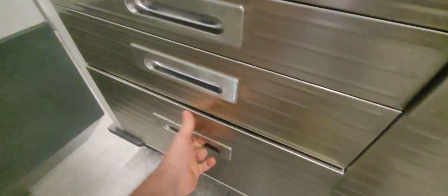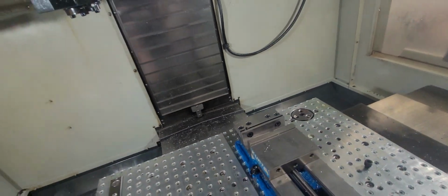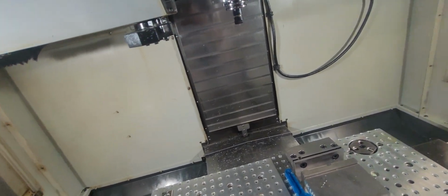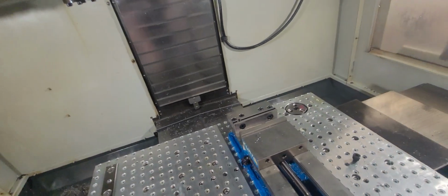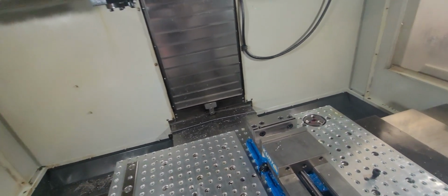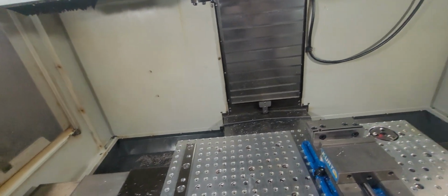Underneath it, because that fixture stays on for a while, I use this silicone stuff. It's waterproof, so when you spray that down and you leave it a little moment underneath there, no rust underneath this chuck. We take it off probably every 3 months, you know, QC what we've got. We've had this system on now for a year. I haven't had to skim it yet, but it wouldn't be a problem to skim it and go again.